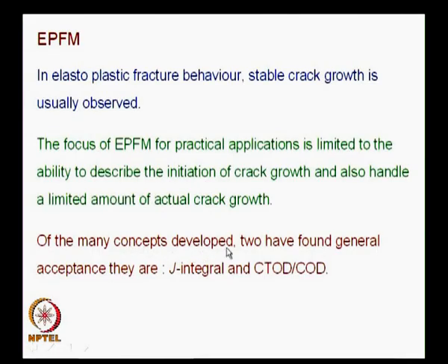Many concepts have been developed in EPFM. Of the many concepts developed, 2 have found general acceptance. They are J integral and CTOD or COD. So, in this class we have looked at the J integral, we have seen its path independence, and I said this path independence is exploited in linear elastic fracture mechanics to calculate stress intensity factor from finite element solution.